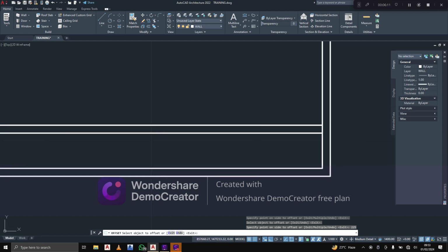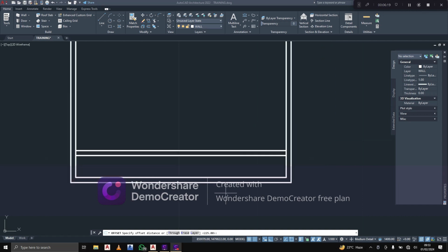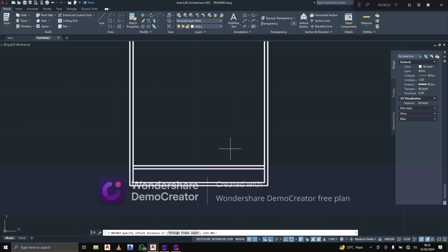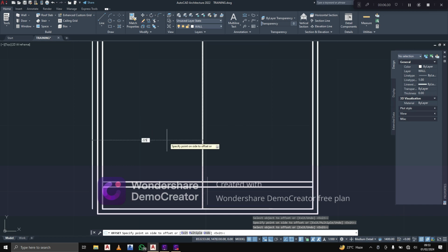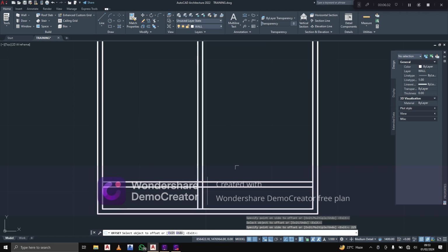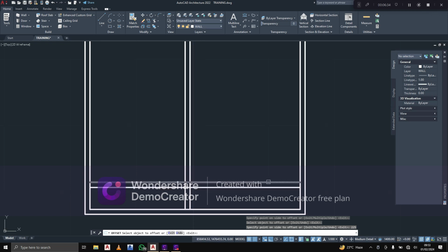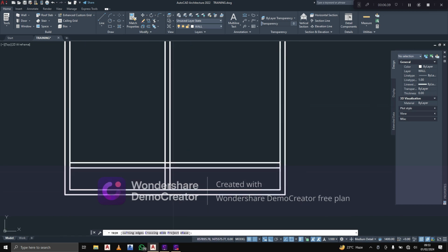Good. So now, how wide do you want your entrance to be? Let's indicate that by indicating our sitting room. Let's just give our sitting room maybe like 5 meters. That's half of our 10 meters. So 5 meters, that's 5 meters. Then your block 225, enter. So this place is indicating our entrance.